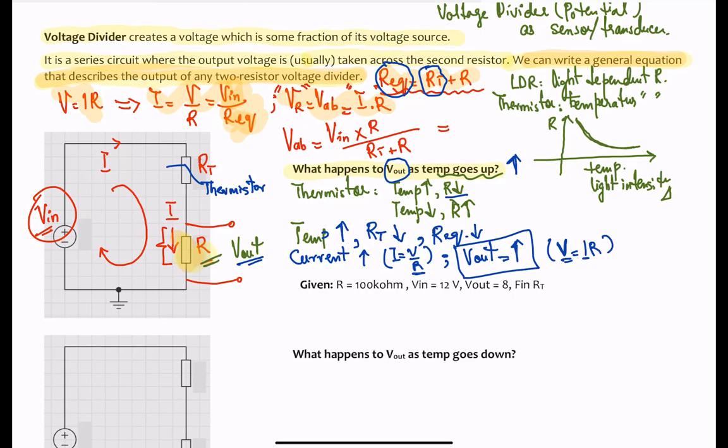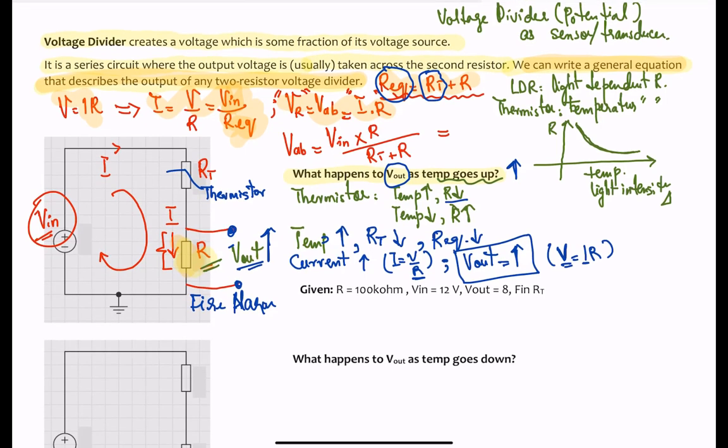Now what we could do here is map the value of this voltage to a temperature. And when this V out exceeds some voltage, say maybe 8 volts or 7 volts, it can trigger a fire alarm or a smoke detector or something. So here you are basically using a voltage divider as a sensor in finding the values.